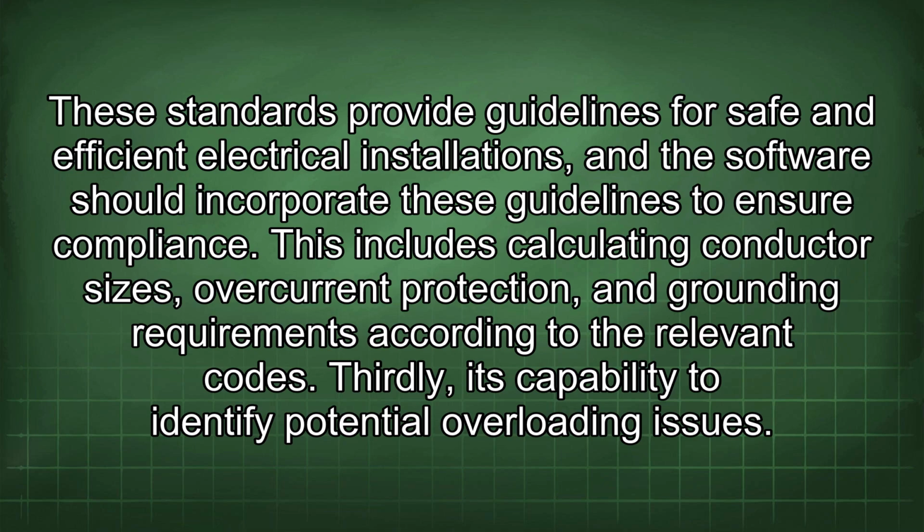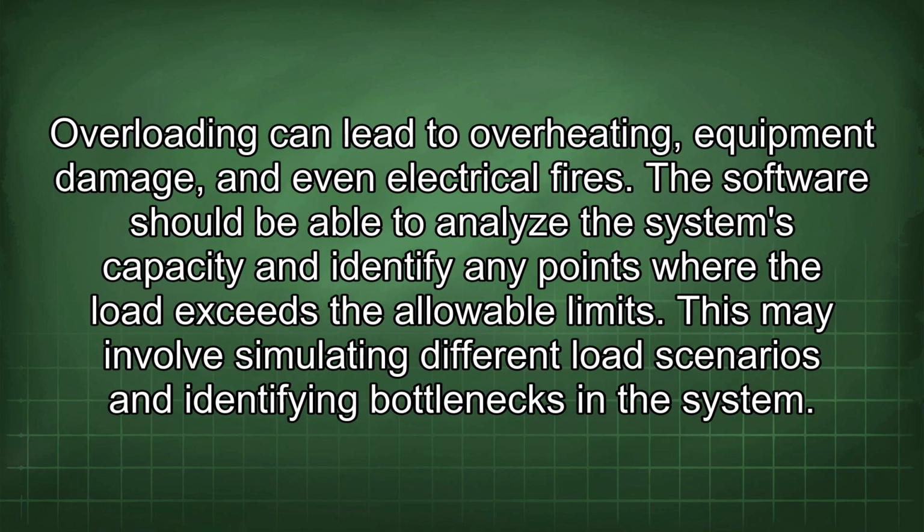Thirdly, its capability to identify potential overloading issues. Overloading can lead to overheating, equipment damage, and even electrical fires. The software should be able to analyze the system's capacity and identify any points where the load exceeds the allowable limits. This may involve simulating different load scenarios and identifying bottlenecks in the system.